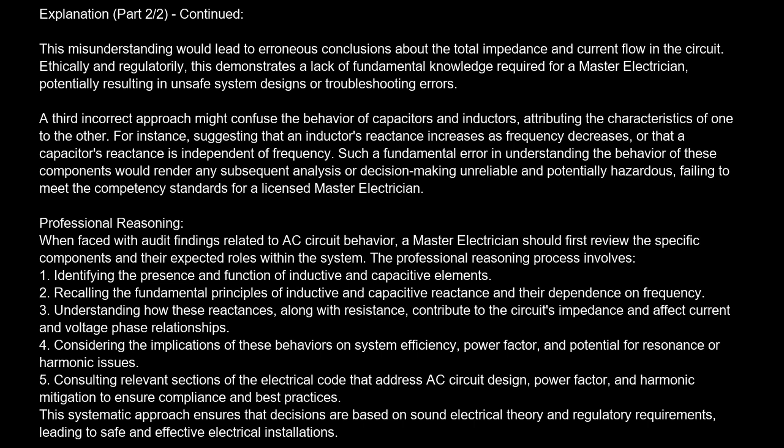A third incorrect approach might confuse the behavior of capacitors and inductors, attributing the characteristics of one to the other. For instance, suggesting that an inductor's reactance increases as frequency decreases, or that a capacitor's reactance is independent of frequency. Such a fundamental error in understanding the behavior of these components would render any subsequent analysis or decision-making unreliable and potentially hazardous, failing to meet the competency standards for a licensed master electrician.